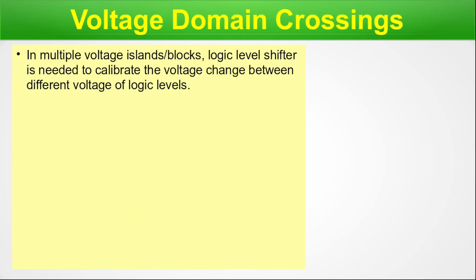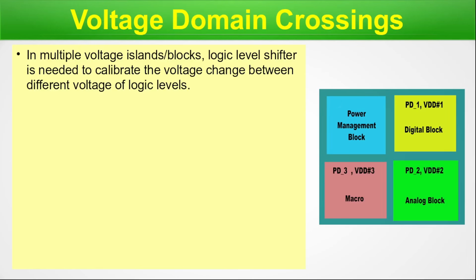In multiple voltage islands or blocks, a logic level shifter is needed to calibrate the voltage change between different voltage logic levels. Here is a brief and neat diagram of multiple voltage domains, or we can call them multiple power domains, managed by a power management block of a modern-day SoC.